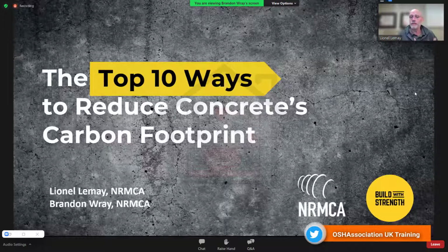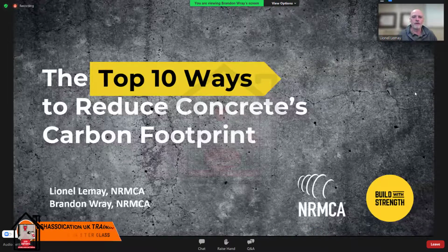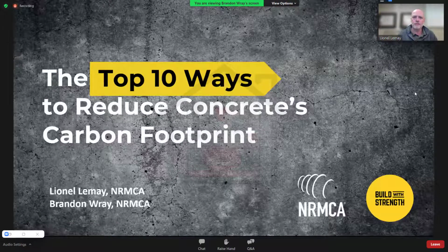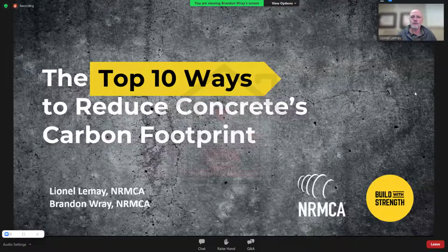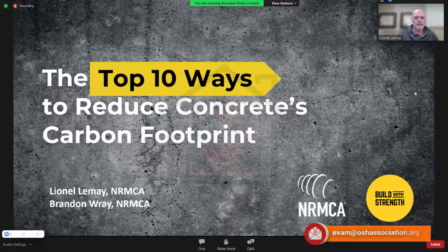The other thing to do is talk to your contractor and really ask them, just like our case study from Los Angeles, they asked the contractor, are you really going to be post-tensioning in 2 days or 3 days, or is it going to be a week? And if it's going to be a week, then why are you asking for this strength at 2 days or 3 days? And oftentimes that's the case. Just like project specifications are copied and pasted from the last project, contractors do the same thing, right? They just always ask for high strength at an early age.